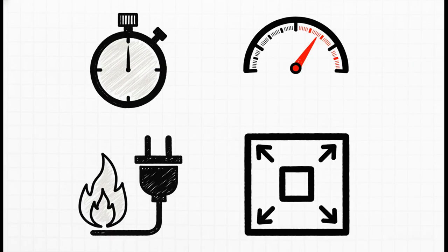First, timing. They have to define the strict boundaries between stages of processing. Second, performance. The physical speed of your flip-flops literally sets the maximum clock frequency, or gigahertz, of your entire processor. Third, power. Charging and discharging these microscopic capacitors requires physical current flow, which creates thermal friction. Flipping billions of switches generates a massive amount of heat. And finally, area. Making these designs as space-efficient as possible saves incredibly expensive, highly valuable silicon real estate.